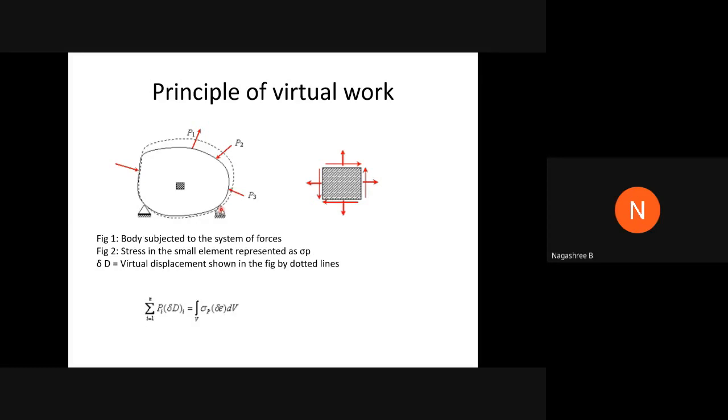These forces and the virtual displacement must satisfy the principle of conservation of energy. Whenever the forces and the virtual displacements are assumed, they have to satisfy the principle of conservation of energy, wherein the conservation of energy states that the external work is equal to the internal work. The work done by the external forces, delta WE, is equal to the work done by the internal forces.